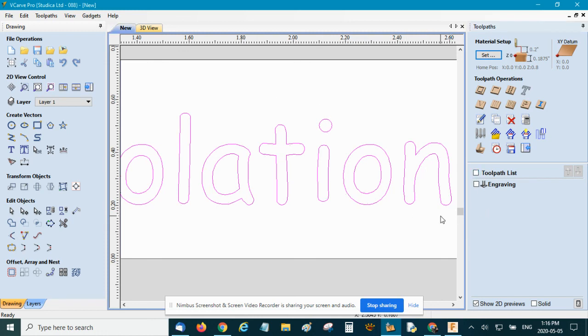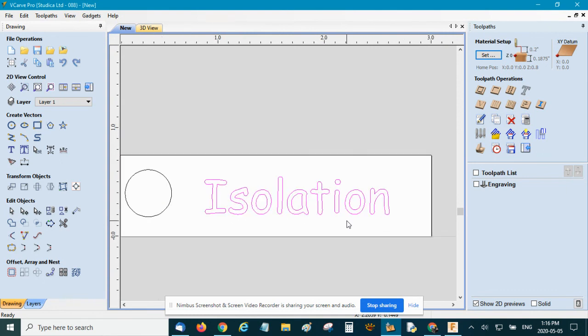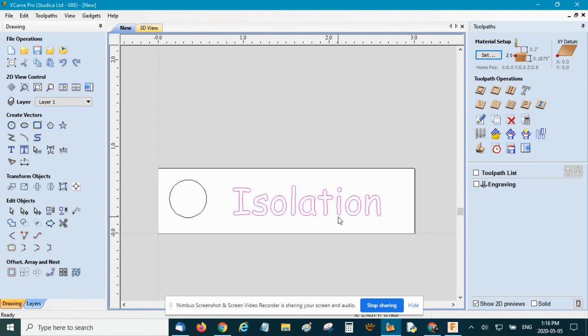Okay, this is the tutorial video to do computer aided manufacturing on Fusion. And I'm going to start with something familiar in VCarve, just to build on some concepts. Remember in VCarve, on the left side, we called it the CAD software, computer aided design, where you design all of these different features that you want. On the right side, there was the CAM part, computer aided manufacturing, where you could go in and do different types of toolpaths and find parameters and features of that.